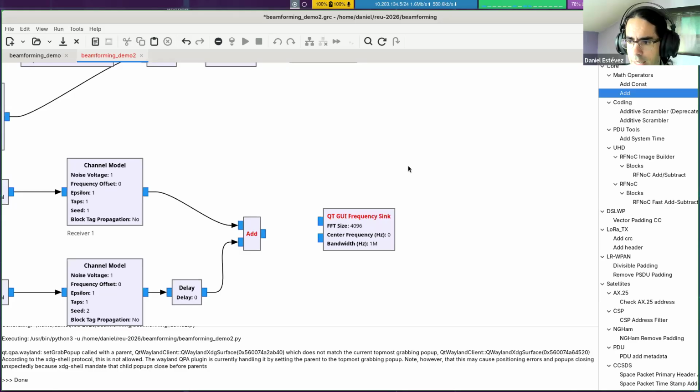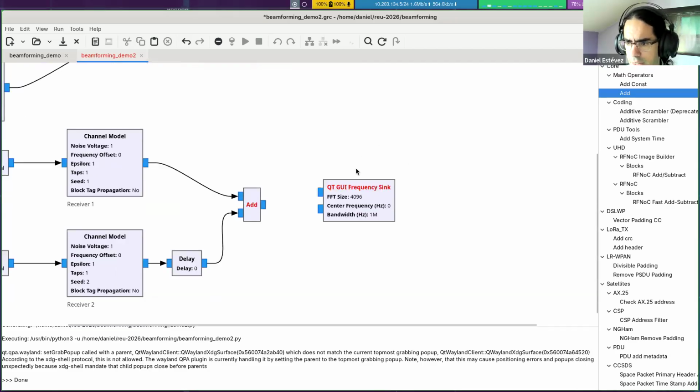And to do that, there is a way of calibrating using sources on the sky, usually bright enough point-like sources such as quasars, to measure the intrinsic delays that we have on our system. So we can measure them, we can calibrate them out, and then the only delays that we need to take into account are geometric delays because of where the source is located with respect to the antenna. So we will see all of that in action next week at the ATA.